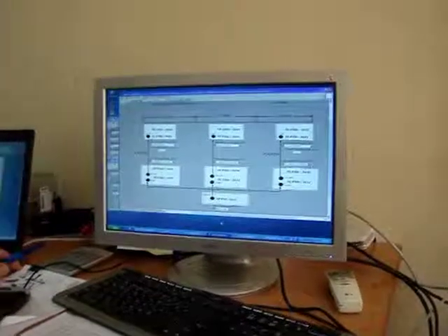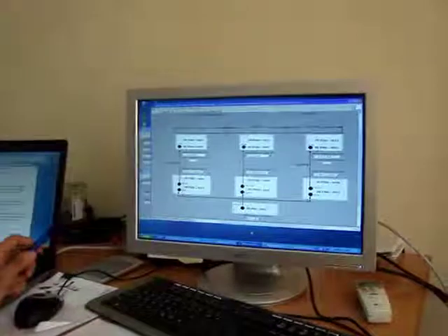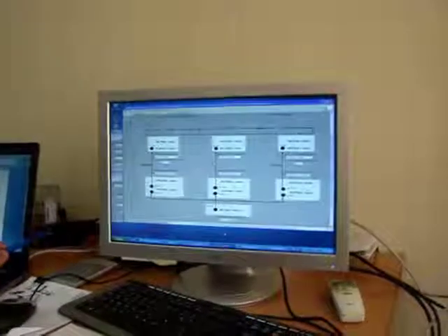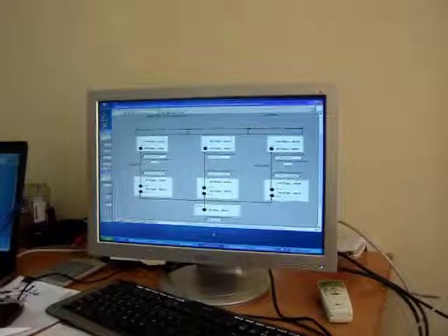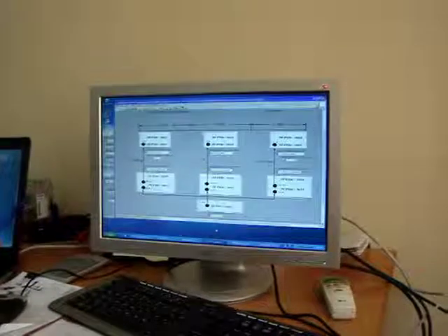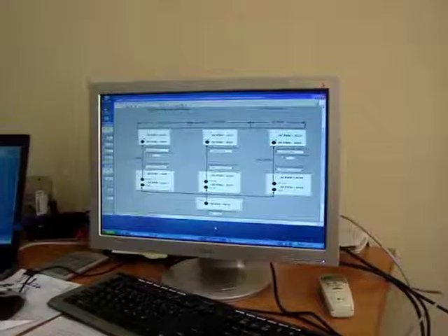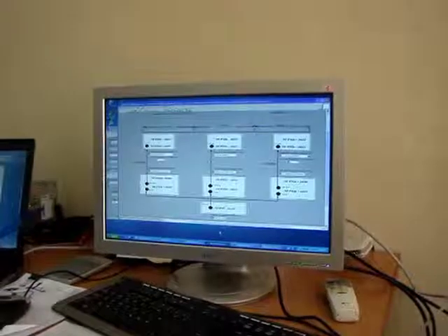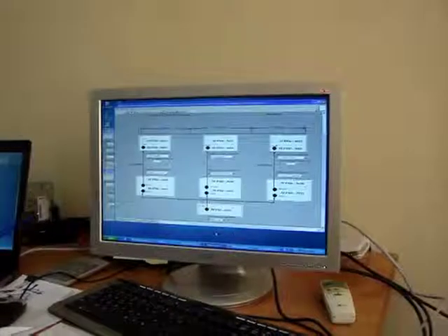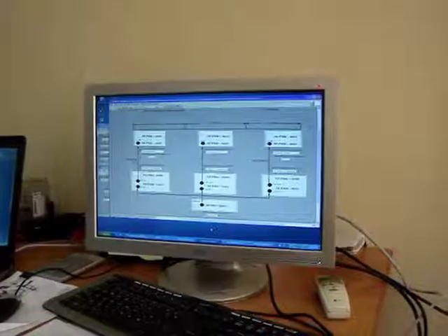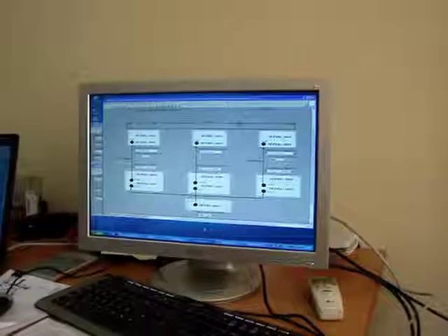The customer needed to record a 60 MHz bandwidth from 10 MHz to 6 GHz. As we know, the PXI Express 5663 vector signal analyzer cannot record a signal with 60 MHz bandwidth. That's why we decided to create the following system.